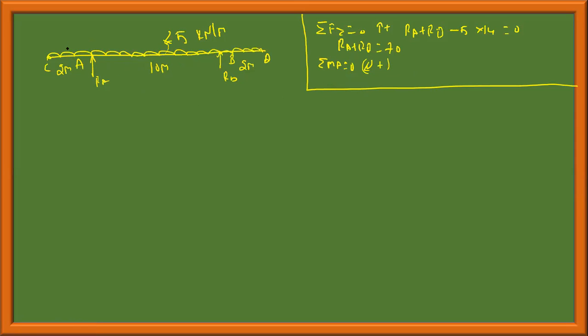this is this force into this distance. This is causing anti-clockwise moment about this point. Part CA: minus 5 into 2 is the load, and the bending moment is minus 5 into 2 into x by 2, where x by 2 is 1. Okay. And this is causing clockwise moment.